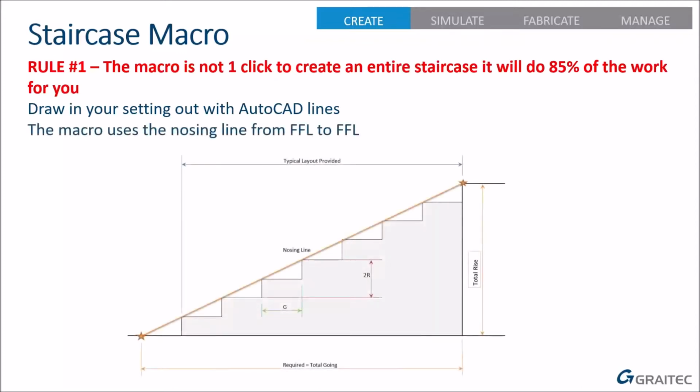In the case of the standard stair macro in Advanced Steel, what it uses as its reference is the nosing line from finished floor level to finished floor level, top and bottom. So the nosing line is the imaginary line connecting the front corner of each tread on your stair. We always know the total rise we require for a given stair. Obviously, we know where the finished floor level is, so we can calculate that total rise, always working from finished floor level.